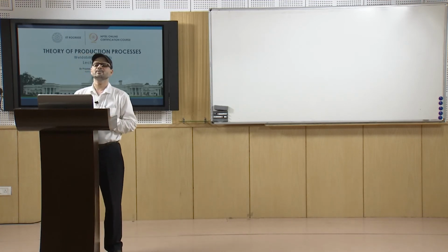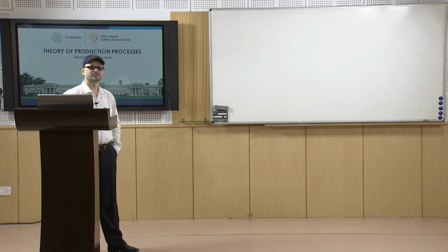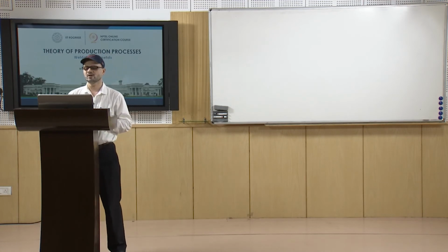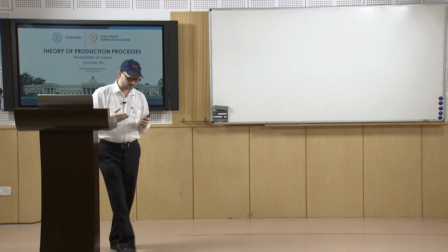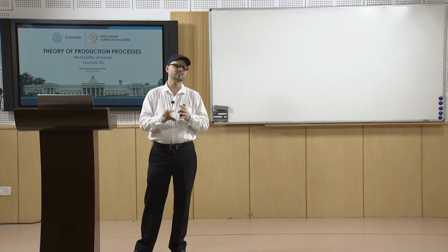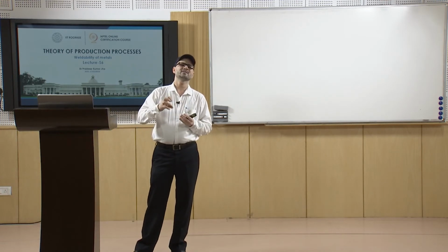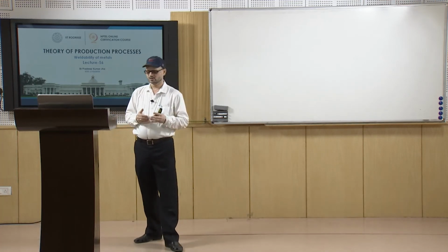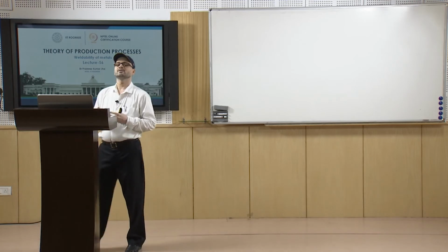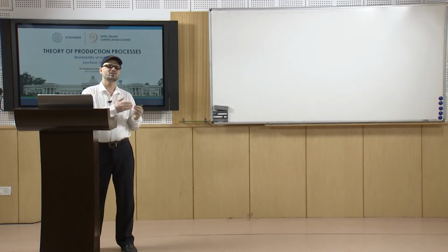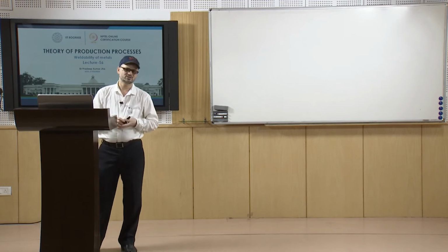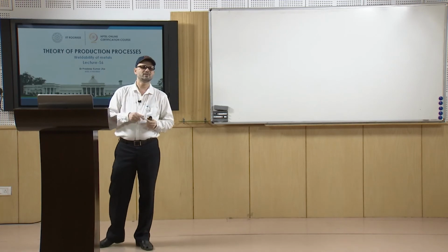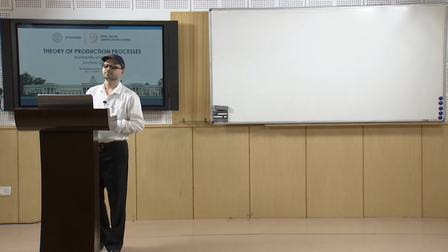Then alloying elements have another important role: they also form carbides. As we know, you have carbide forming elements, and they form carbides and provide hardness. For example, vanadium or tungsten are strong carbide forming elements. They may affect the weldability of the material.